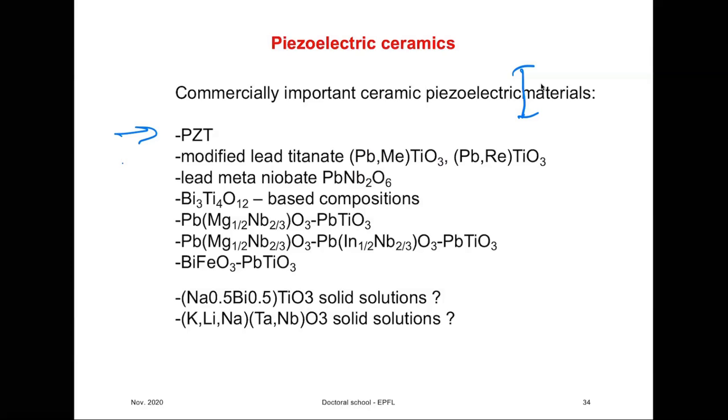These materials are also interesting because they have a very large anisotropy in piezoelectric properties. So d33 can be large, 50, 60, while d31 can be 0 and can even be positive. So small negative, 0, or a small positive value. And this is very interesting in some applications where you would like to reduce transverse piezoelectricity. Right now it's handled mostly by using composite materials, but in cases where ceramics have to be used, for example, there are acoustical microscopes and so on, where you want to have very high directionality of the sound wave, people sometimes use lead titanate based materials.